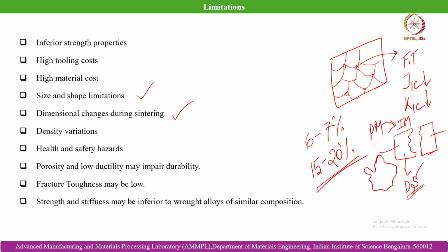A classic example is sintering a cylindrical object, which is a green compact. It can face sagging, or it can become dumbbell shaped. It is a severe distortion because of the shrinkage and inward diffusion of the matter present at the surface. So, often dimensional tolerance control demands extra precautions, and that is why it also increases the cost of the process.